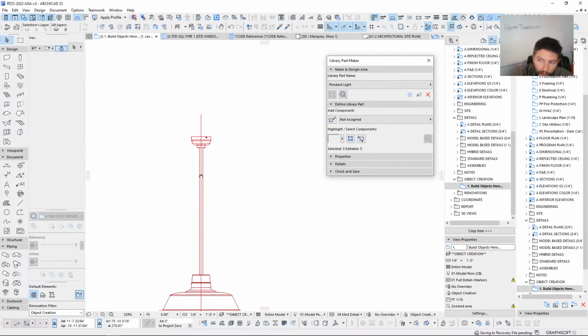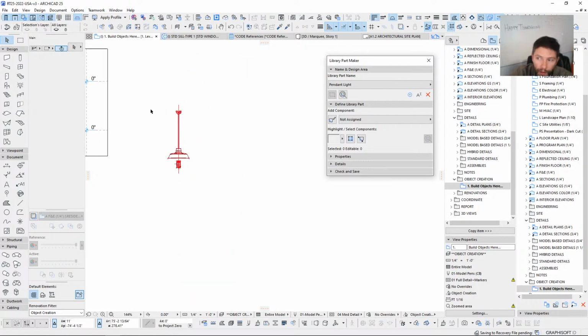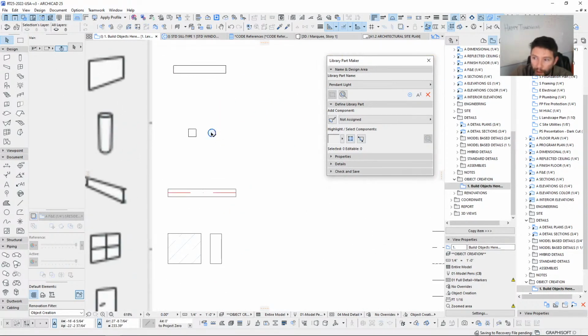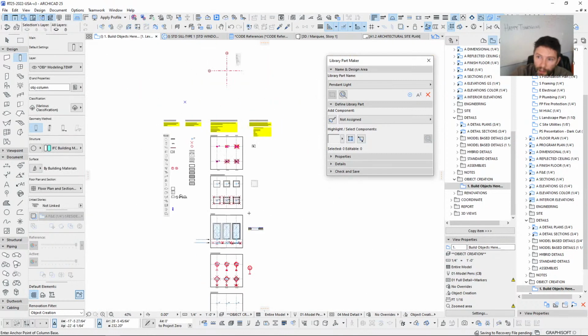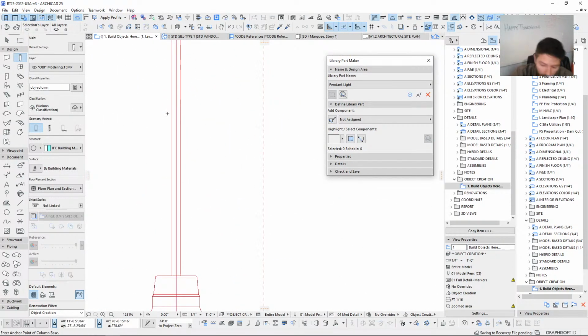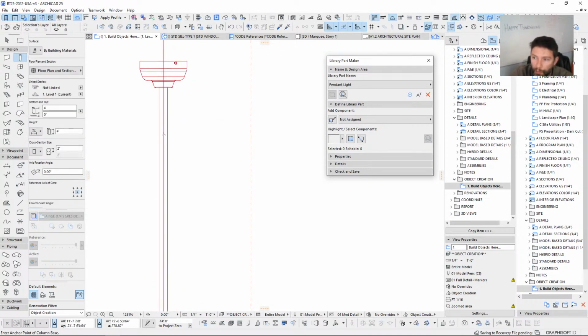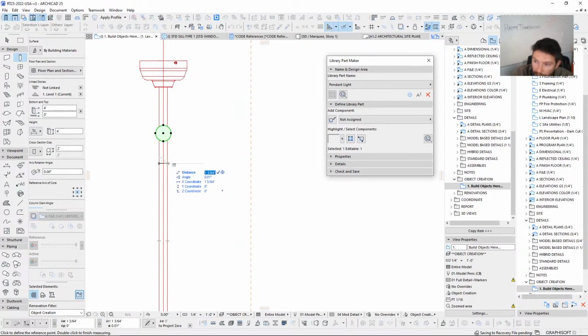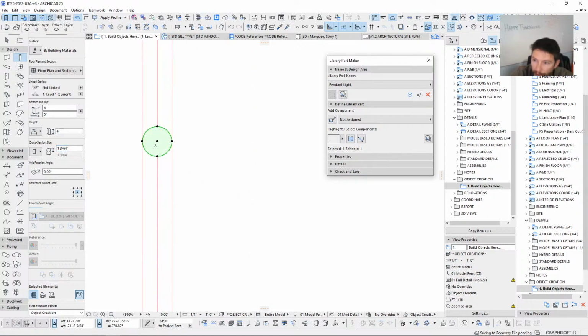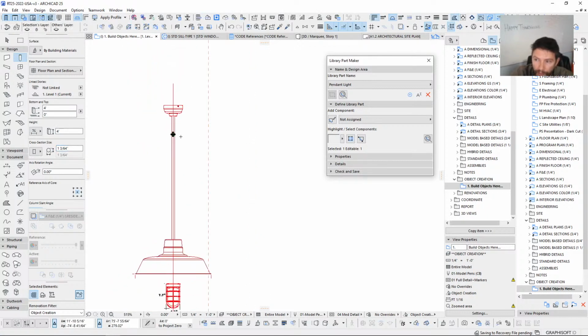Now, this next segment we will add with a column later on, but let's go ahead and grab a round column in this case, and do a quick measurement to see what our width is. So we're just over 1 inch there. Let's do this: we can measure, hit D, copy, and then paste, and that will set that exactly to that size there.